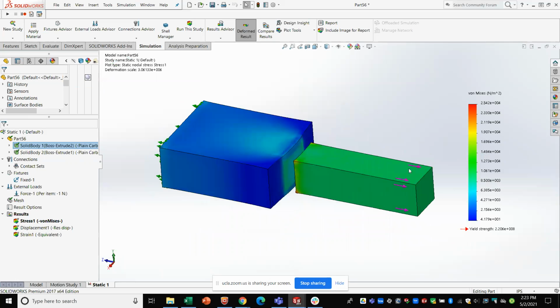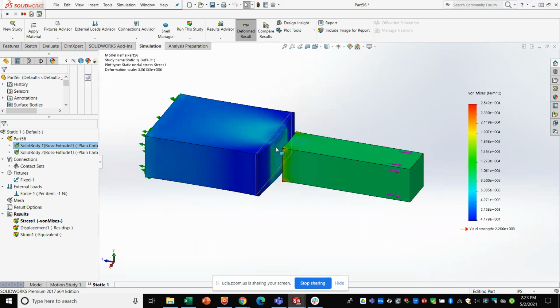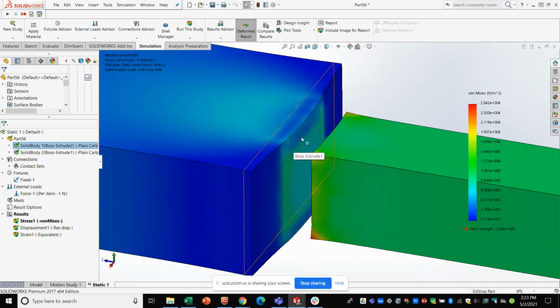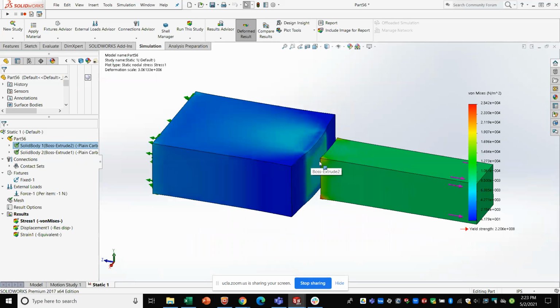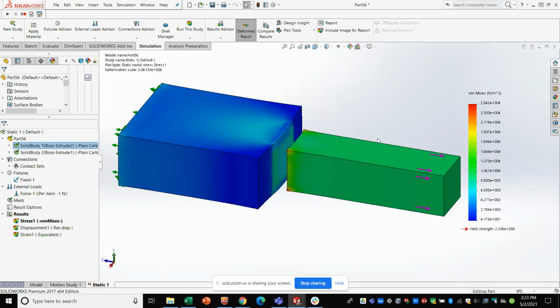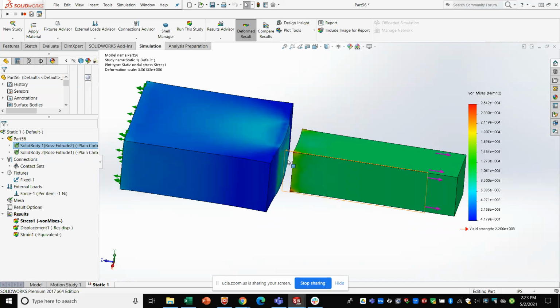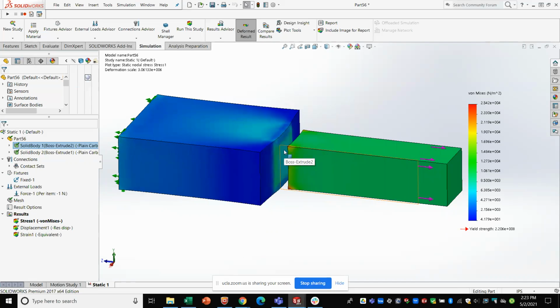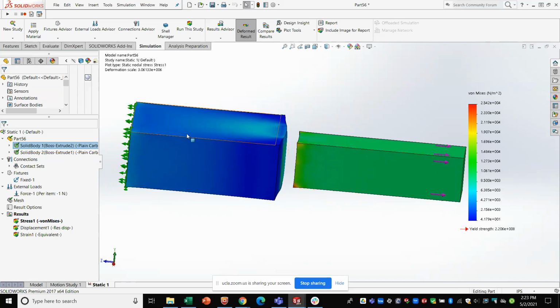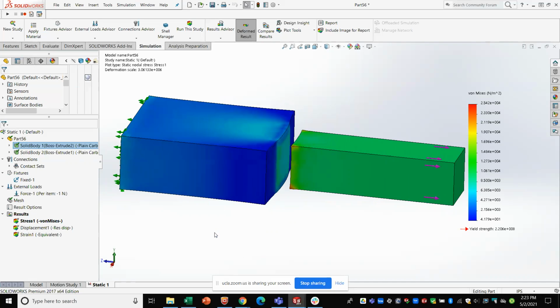And this is important because what's going on under the hood, where it's forming these individual elements, these little tiny springs between the two faces, is just as computationally efficient as simulating a single solid part. As long as all of the parts in your entire contact model are bonded together, it will simulate just as fast as a single part. There's no computational penalty for it. But you can also get some inaccuracies. Case in point, these parts are not touching, and yet it's telling you that this part is physically capable of pulling on this part. It's not really realistic.